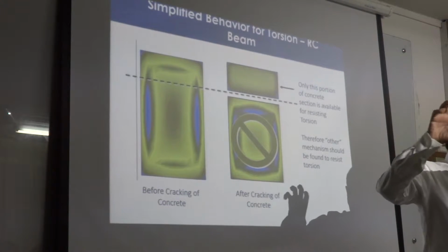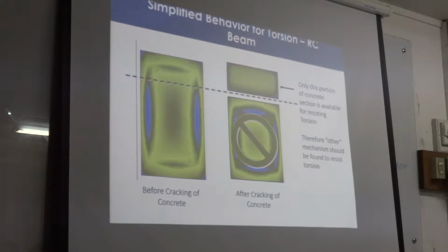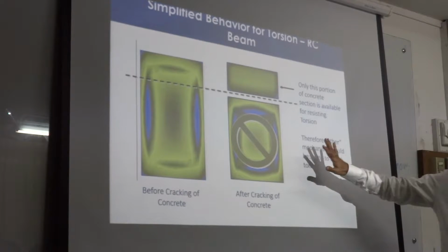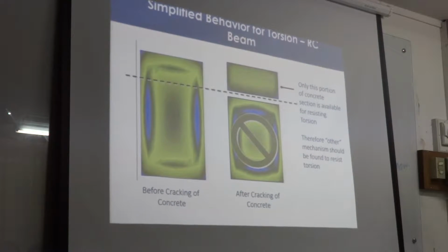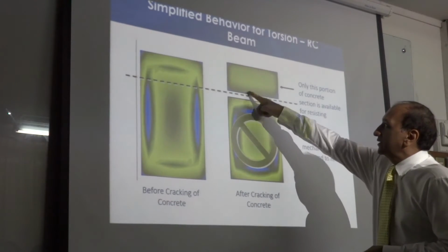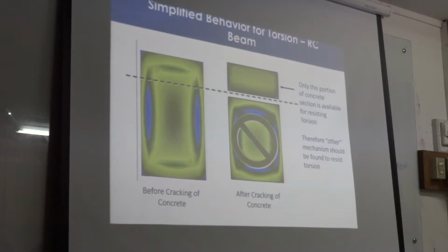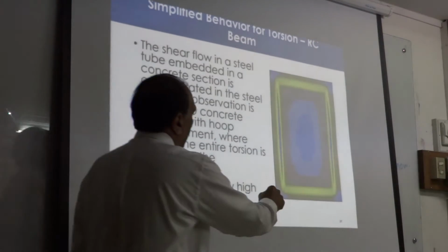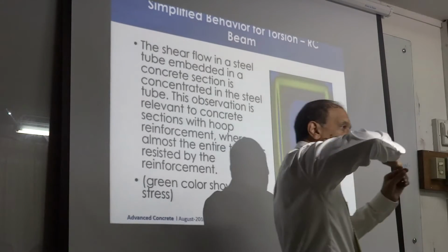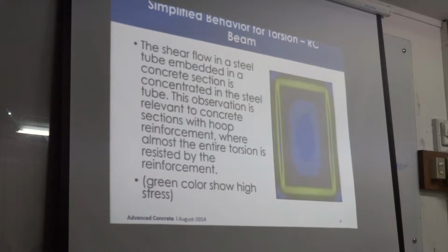In a normal beam, at the end where we have maximum shear, we have no bending, so we have no problem. Correct? But when it is a continuous beam, you have a lot of negative bending and a lot of shear coming at the same location. So in those locations, and also for earthquake loading, which can have varying moment directions, we normally do not consider the contribution of concrete in shear. And so we can basically neglect all of that, and only a small portion is left, which is in compression. So it is advisable to design for torsion primarily by reinforcement, because torsion is a stress around the edges of the section, and we can just put the reinforcement there and we should be fine.